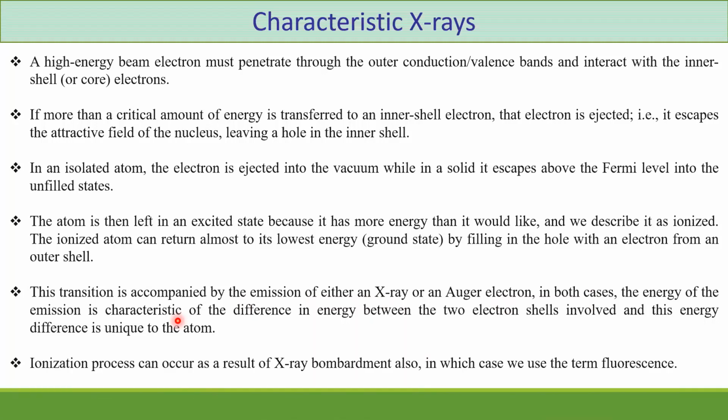The ionization process can occur as a result of X-ray bombardment also, in which case we use the term fluorescence. If you remember the first material characterization talk, I was talking about X-ray fluorescence spectroscopy. Just as an electron bombarding the material gives X-ray through the process described here, there is also the possibility of X-ray bombardment giving X-ray through a similar energy filling and energy balance process. That's why we call this X-ray fluorescence.